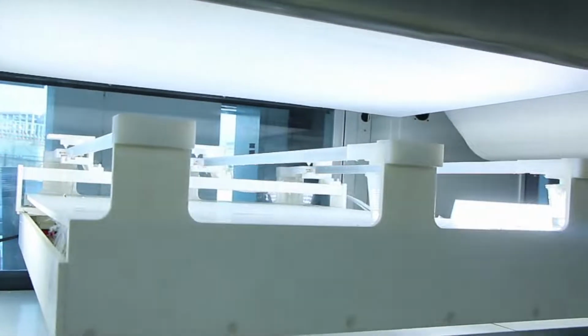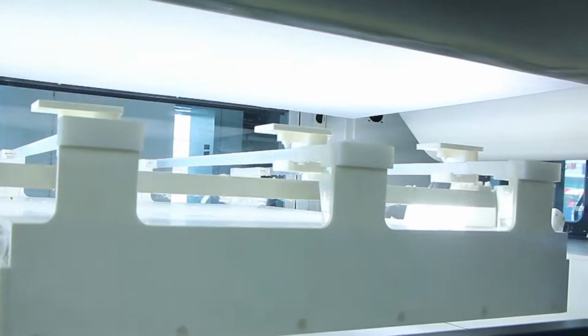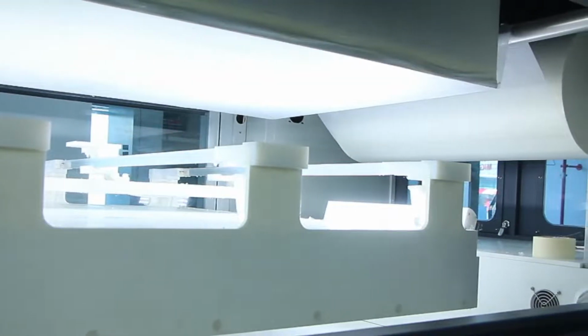Okay, now my colleague just helped me here. He just filled the solution on the surface of the spinneret, and we're going to be starting production soon. First the feeders, the white Teflon needles, insert the solution onto the surface, and after it gets filled completely, we will activate the high voltage, and you'll be able to see some spun jets soon. So we can begin right now.